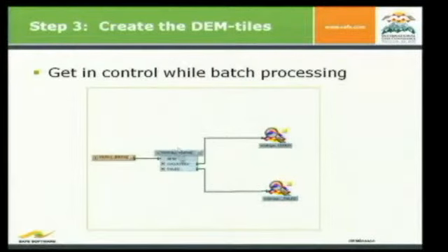So you have actually added two very important transformers. It's a reader actually, and this is the FilePath reader. I don't know how many have used this one. This one in combination with the WorkspaceRunner is really a great thing, because what it does, the file path and memory just reads where the files are. You can throw in a wildcard and you get a list of all the files and the path to the files. So in this case, when we run this, I would get 700 features, which only is a path to the laser scan data.